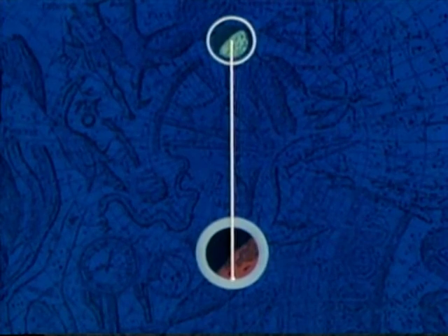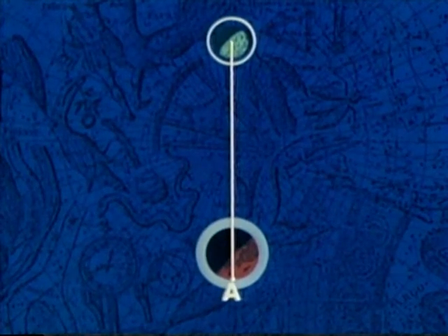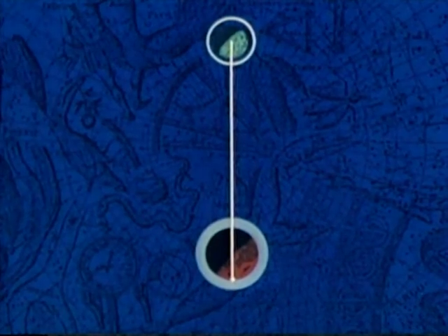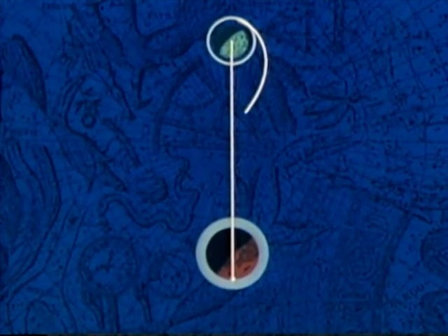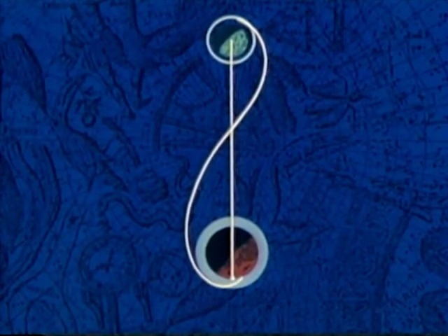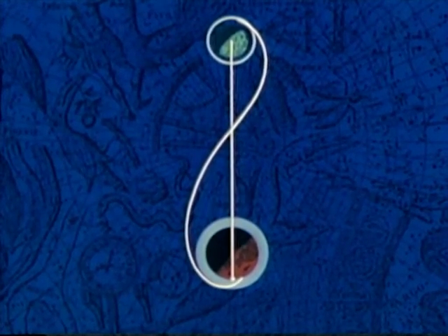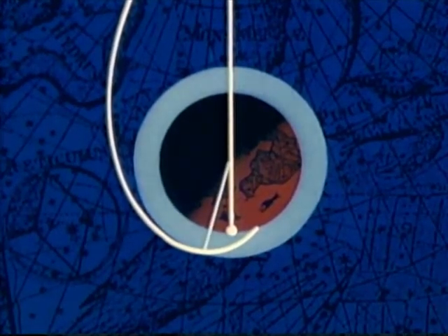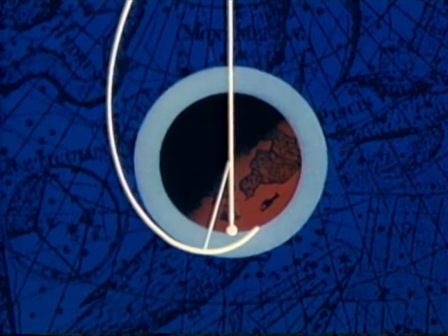A line is drawn from the center of the Moon through the center of the Earth, penetrating the Earth's surface, which faces away from the Moon. The point of penetration is called the antipode, which means simply the point opposite. The return trajectory will pass over the antipode, being determined at the time the spacecraft leaves the Moon's vicinity. The distance from the point of entry into the atmosphere to the antipode is relatively fixed.